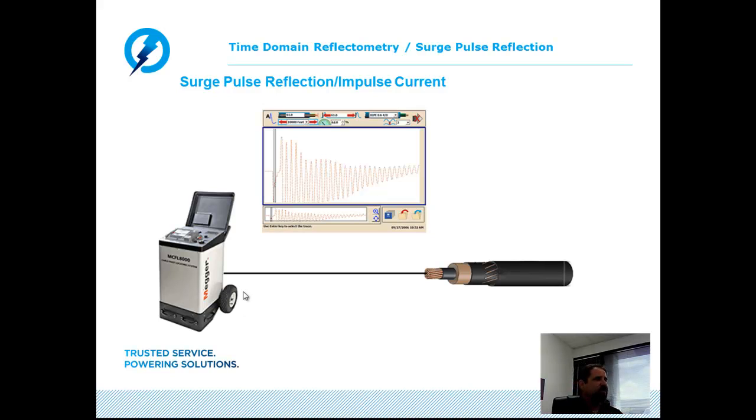Now, what we're seeing in this waveform is when the high voltage capacitor discharges, that discharge creates a current transient passing the internal CT, and we see that outgoing current transient on the oscilloscope. Now, when the cable fault actually flashes over, it's sort of like a thumper thumping back toward the test equipment. So at time period number 2, we see the returning transient caused by the arc established on the cable.